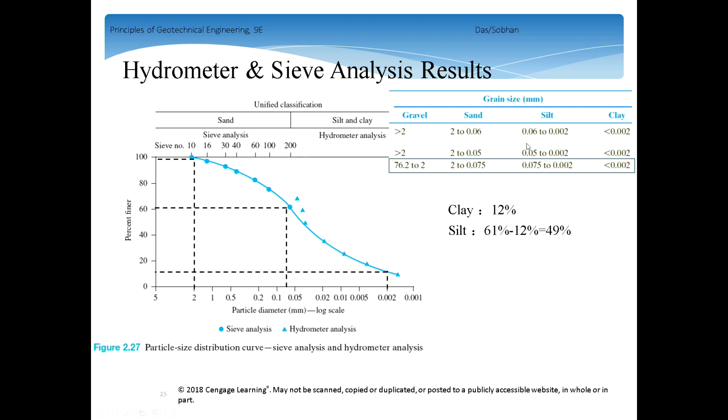And if following this code, it asks you to find the sand particles, it is 0.075 to 2 millimeter. So 2 millimeter is about in here. And the sand then accounts for, this y-axis is about 98, right? 98%. But the 98% includes what?